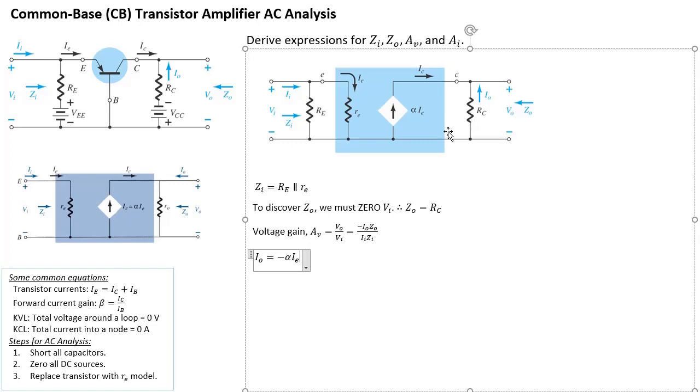Okay, so very simple. So in the case of II, what can I write? Well, actually, you can write a relationship between II and IE, because IE is obviously a current divider, right? So II splits between that flowing through capital RE and IE that is flowing through little re.